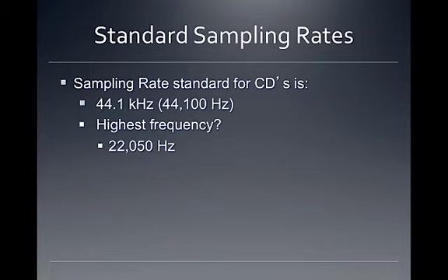It's going to have a bit of a slope to it. So we move the filter up to 20,000. The frequency would be at 20,000, and then it gently slopes down into 22,050 hertz. So we said everything pretty much above 20,000 we don't necessarily need to record for our human hearing.